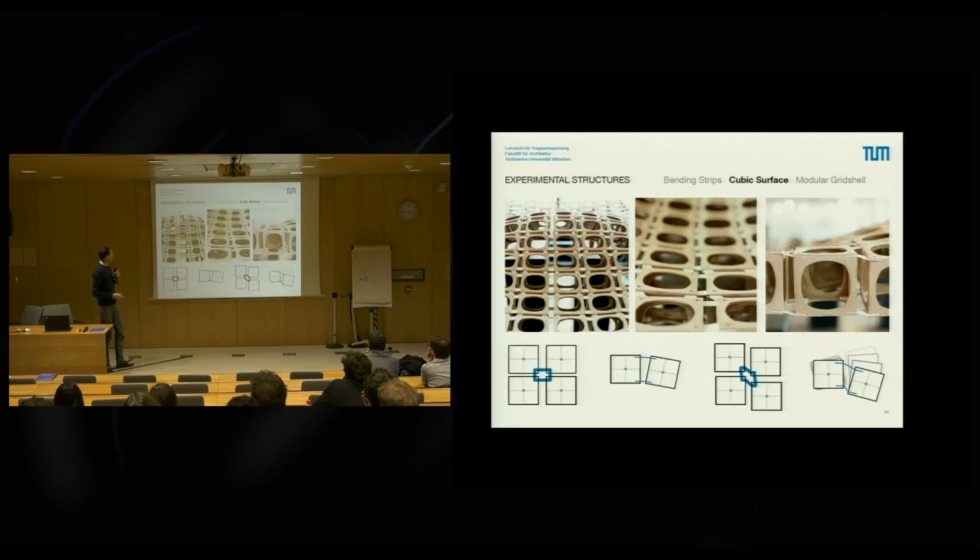So we started looking at this, and we very soon noticed that it was not only the distance between cubes. First we thought just distance on top, distance on bottom. But then we noticed there was actually also, of course, a kink in there. And then if you walk along the grid, you start getting a shear between the different modules. And because you get the shear, 2 related modules also are torsioned, especially if they don't run along the principal curvature lines.